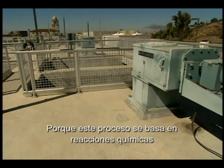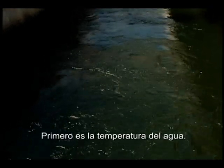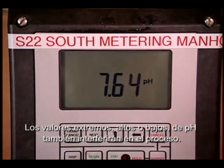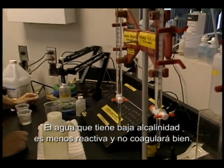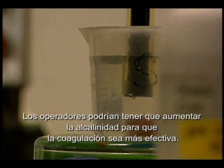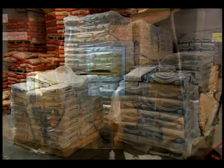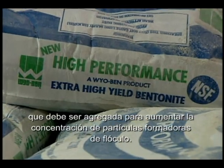Because this process relies on chemical reactions, several considerations must be made. First is water temperature. Colder water usually slows coagulation and flocculation reactions. Extreme values of pH, high or low, will also interfere with the process. Water with low alkalinity is less reactive and does not coagulate well. Operators may need to raise alkalinity for coagulation to be effective. Turbidity is also important. The lower the turbidity, the more difficult it is to form proper floc. Sometimes a weighting agent, such as bentonite clay, may be added to increase the concentration of floc-forming particles.